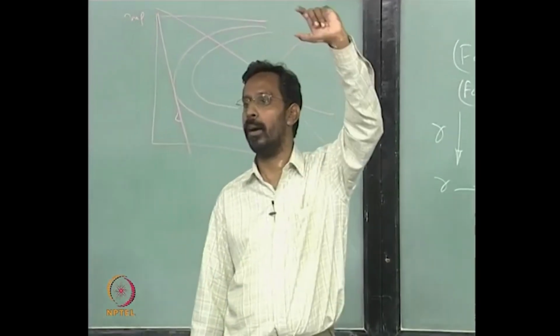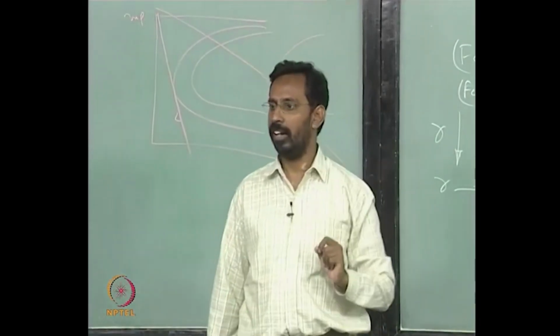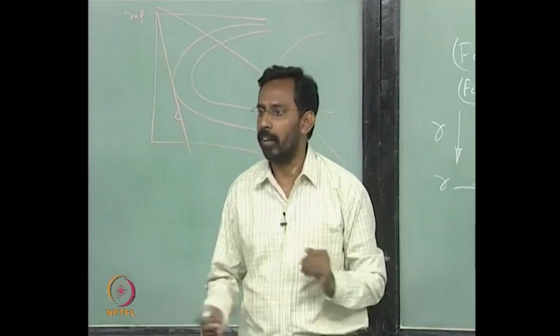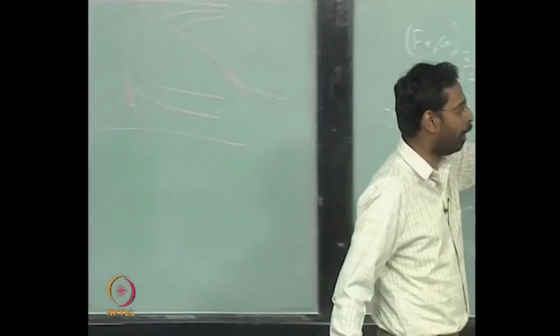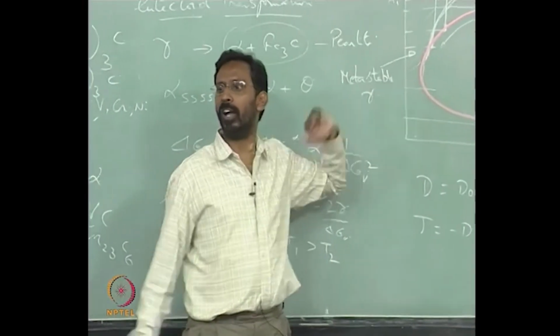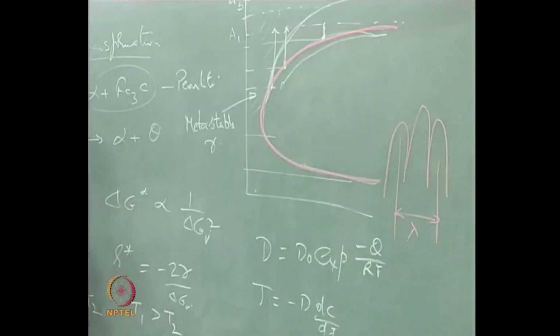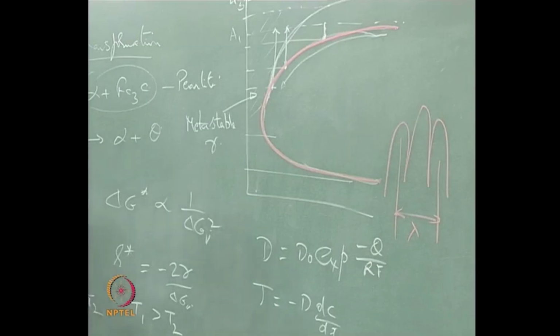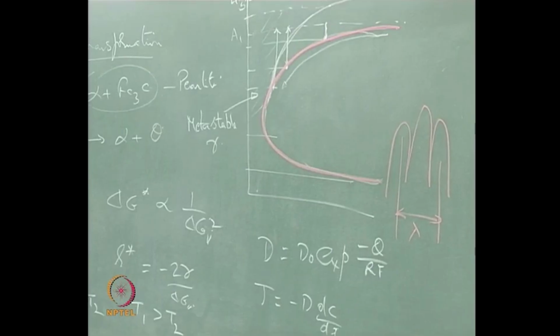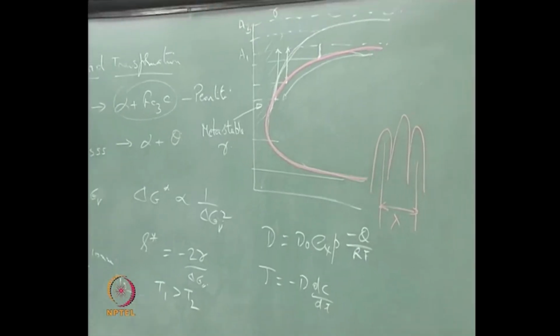And now once you have them, now I am quenching it, let us say I am not providing sufficient time, I have brought it to a lower temperature here. At that temperature now I have to see what happens to this steel. I have gone to the solution as well, sir. I finished it. Again I want to form niobium carbide. Since I got a strong affinity, it has to form at low temperature now, sir. Correct. I do not need to go to high temperature, I am quenching it to a lower temperature, but at